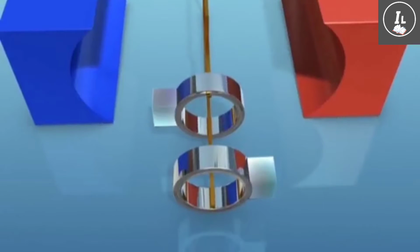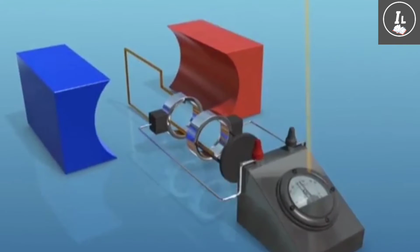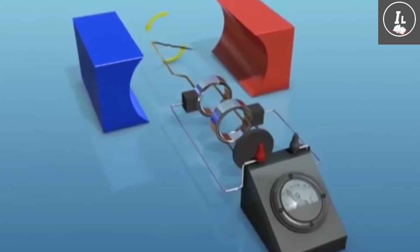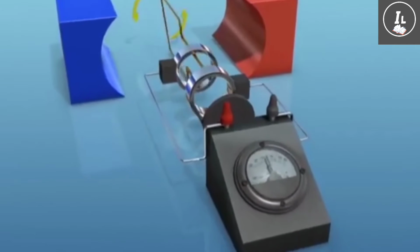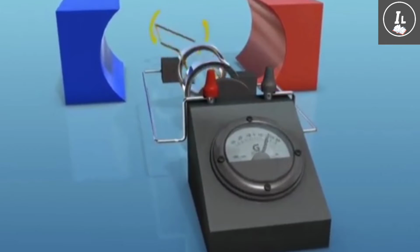One end of each brush is in contact with rotating slip rings and the other end is connected to an outer circuit. A galvanometer is connected in the outer circuit to show the deflection due to the current induced in the armature. When the coil is rotated between the pole pieces, a current is induced in the coil. The induced current is shown by the deflection in the galvanometer. The two-way deflection in the galvanometer shows that the induced current is alternating.